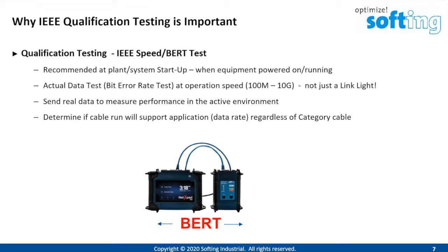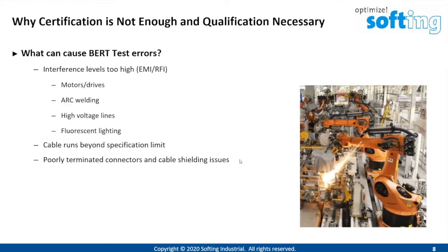These tests are much more in depth than just looking at DC continuity, which a lot of the low end testers do. That's the other end of the spectrum: does pin 1 go to 1? Does 8 go to 8? So having the means to do speed testing over the cable is really good practice for industrial settings.